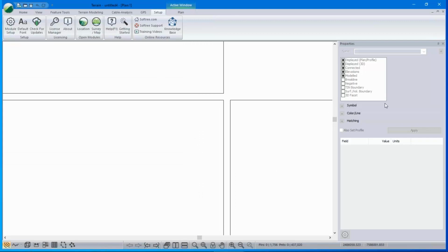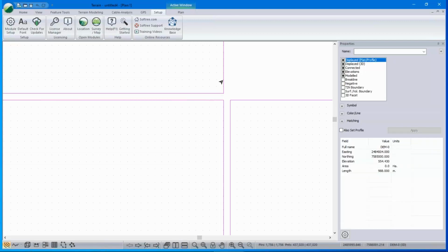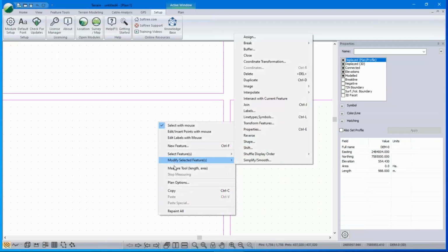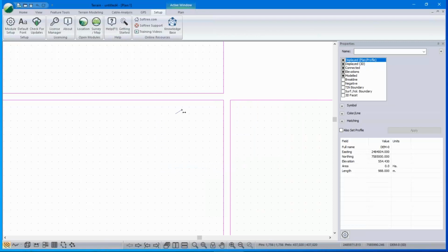And if I look at that, you can see the grid points there. And I can measure between them, and they should be 4 meters apart, because the original grid was 1 meter, and I skipped 3, read 1. So I've got 4 meter spacing instead of 1 meter spacing. And that reduces my data a lot.